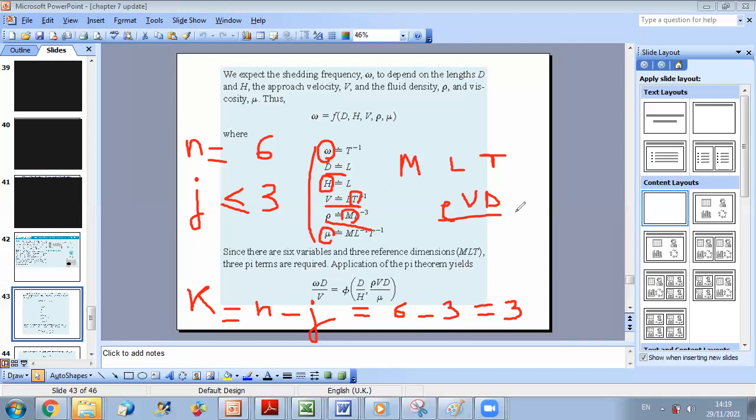As I told you before, you have several ways to determine groups. You can use the Buckingham theorem. Okay, in general, they should specify the method to use for you, and if not, you can use what you want. Some of the groups you will recognize directly, for example, mu with rho v d will give you Reynolds, because this group will come up for you a lot. So you can directly say that the group with mu is mu over rho v d.